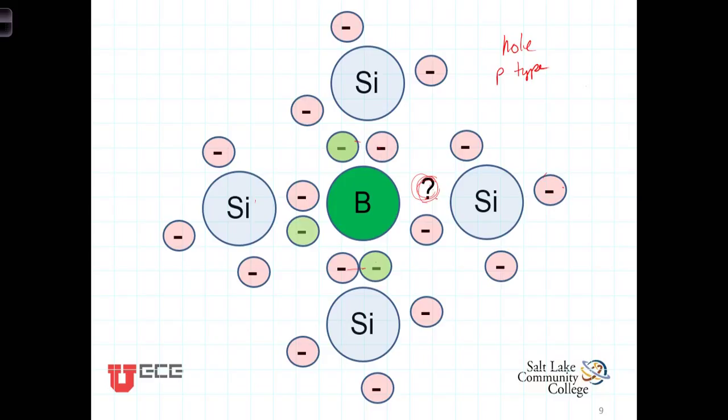So we can dope with N-type dopants, such as phosphorus, that provides a free electron, and we can cause that to carry charge. Or we can dope with boron that creates a void, and in a similar way, placed under a voltage, we can cause these voids to move from one point to the next and create a current which is known as a hole current, that is analogous to an electron current, but it goes in the opposite direction. It flows in a different voltage direction.